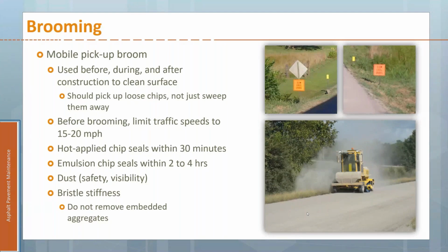So there is that intermediate period where it's difficult to work with, but it's fine for traffic to be on it, just not optimal for them to go too fast. And rocks in the windshield are one of the most common issues. So put up a sign, slow, we've got loose gravel. One agency that I know of puts up signs that say fresh oil, and they said that slows people down more than anything. And technically it's true, there is fresh oil, it's under the rock, but it is there. So whatever works, however you can get folks to slow down, that's great.